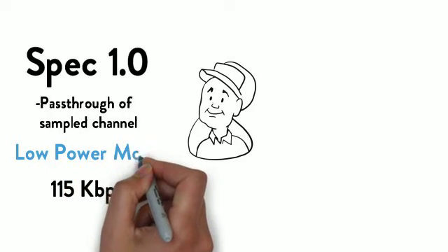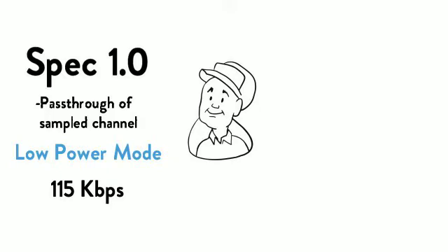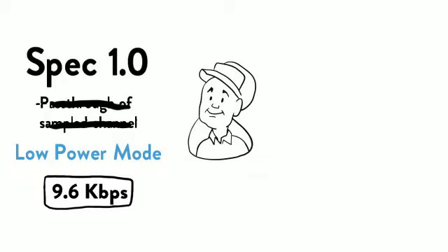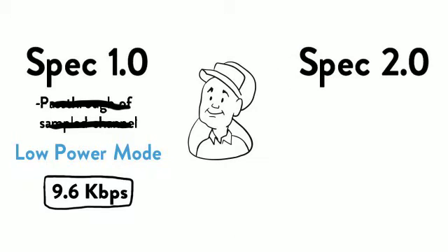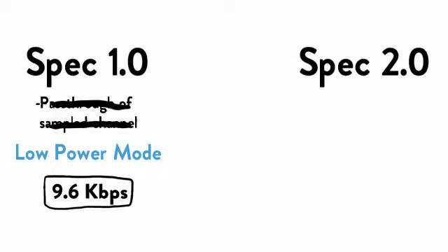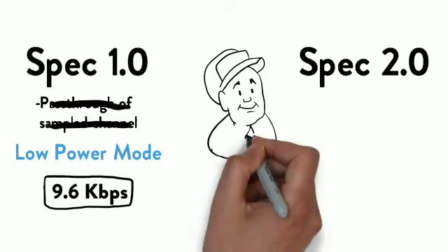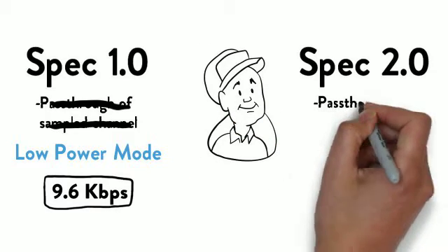If the product supports low-power switching mode, the system switches to power save mode to comply with green regulations. And then the baud rate is limited to 9.6 kilobits per second, since RS-232 as a standard does not support dynamic baud rate changes.